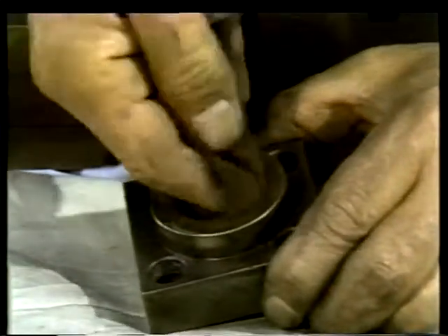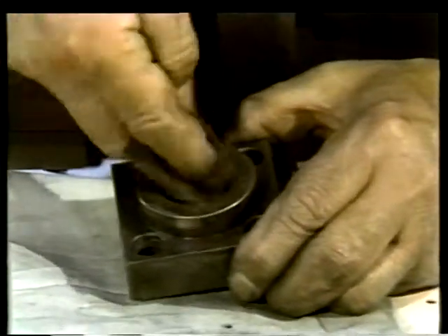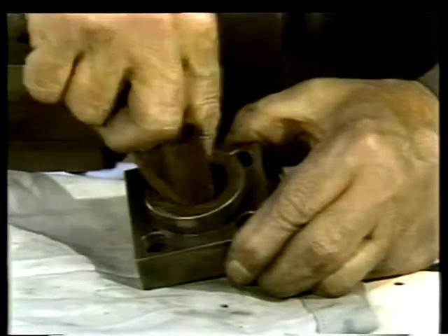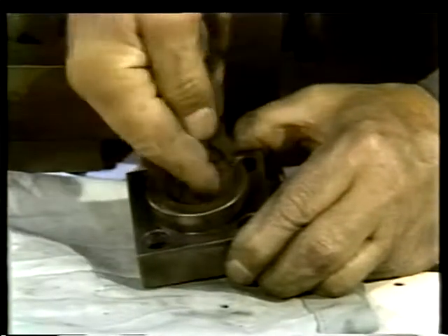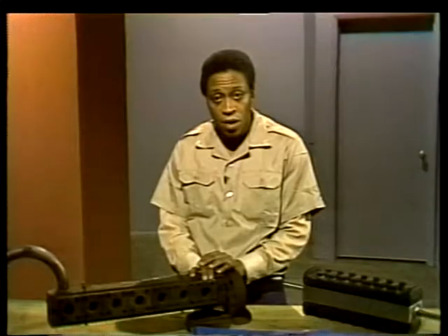During the parts cleaning, wipe off any particles of the cushion gasket that might be on the cover plate gasket seating surface. If the cushion gasket sticks, soak the cover plate in hot water. This should help remove the gasket.